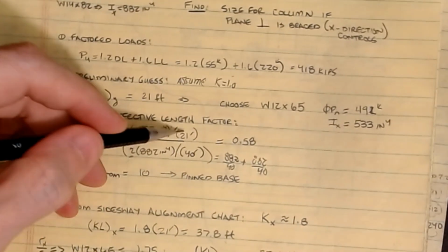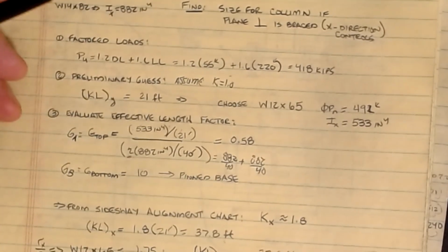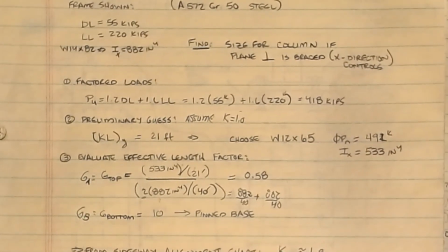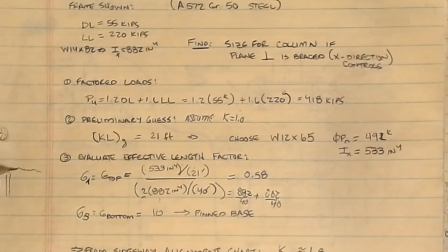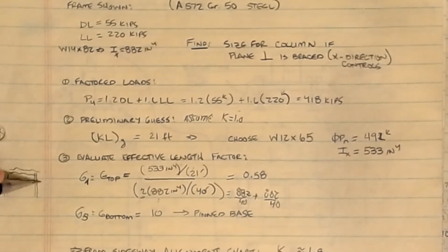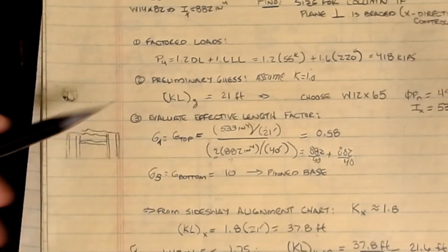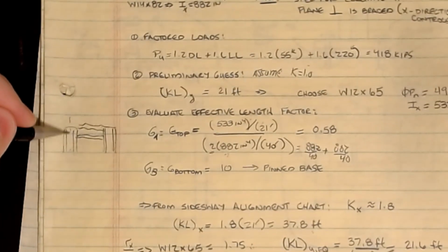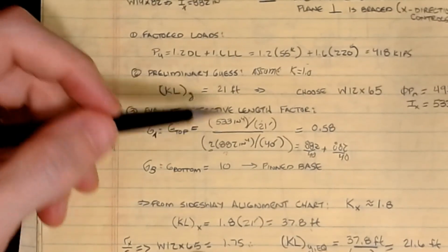So here's IX over its direction, and we're going to assume that we're bending with respect to the IX. If you're bending with respect to IY, you need to use IY here. So what we've assumed is that all the columns are oriented this way, and then the girder is coming in and doing something, so that all the orientations of the members look like that. So the moment you do this calculation here, you've set the orientation. Okay, so this is the strong axis orientation that we're looking at relative to that column and so on. Okay, so I hope that's made sense.